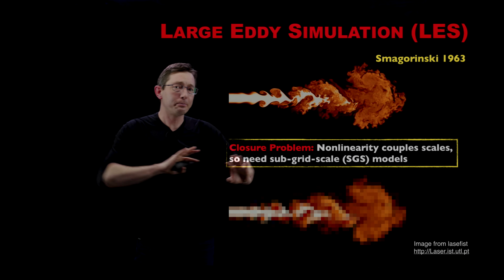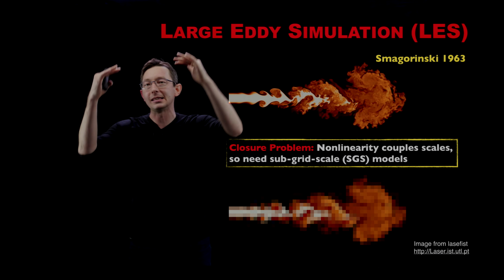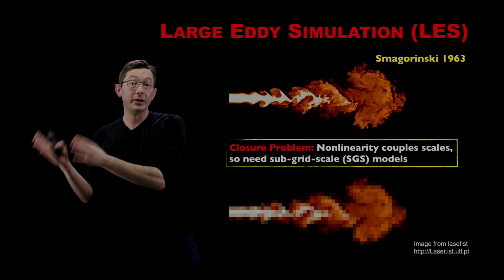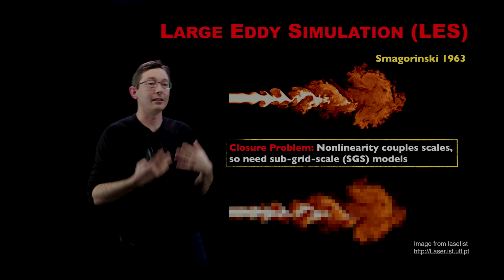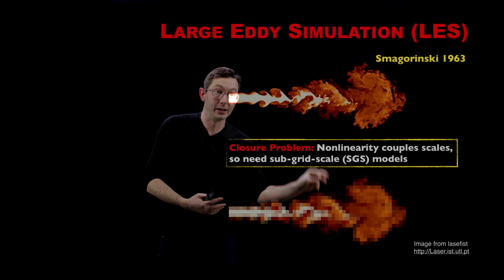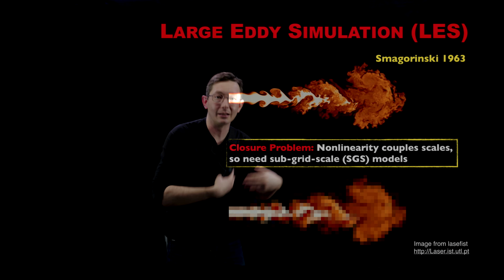In principle, for LES we have kind of the same tool set that we did for RANS. We're going to use eddy viscosity modeling and things like that. We're going to make hypotheses about what's happening behind the scenes, underneath this coarse grid, in the full resolution field. And we're going to make approximations about how that's approximately acting like an effective viscosity.